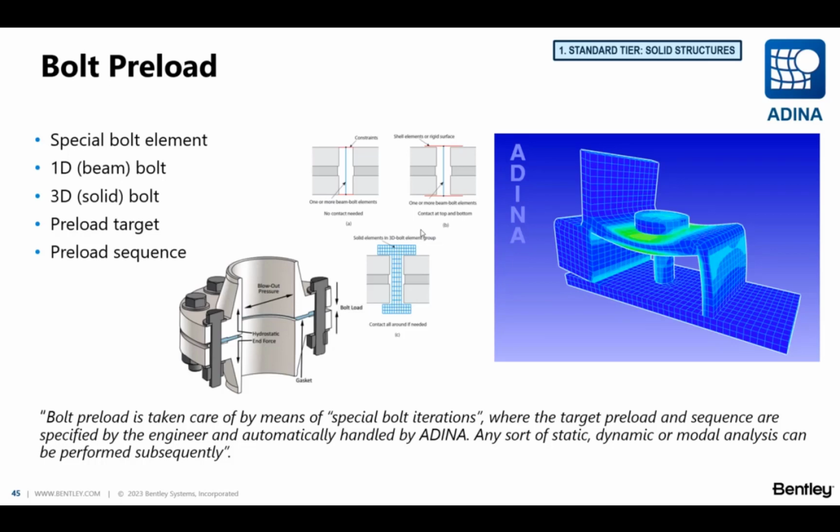So in Adina, we don't need to do that. We just specify the target preload, the final preload that we need, as well as the sequence if we have many bolts on the structure, like that connection to the left-hand side.